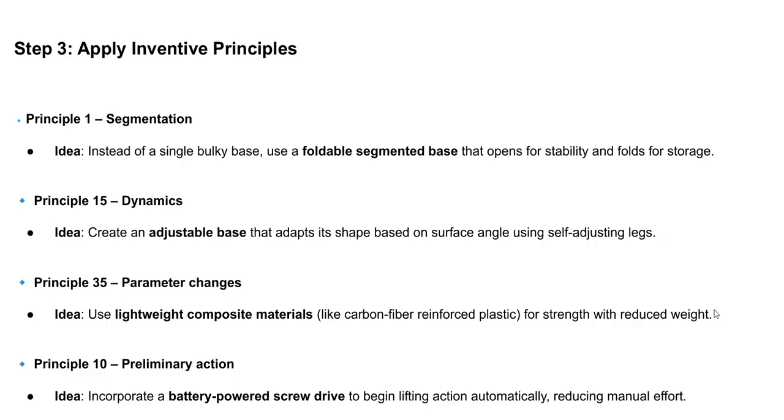Step number 3 is to apply the inventive principles. First principle, segmentation: instead of a single bulky base, use a foldable segmented base that opens for stability and folds for storage. Principle number 15 is dynamics: create an adjustable base that adapts its shape based on surface angle using safe angle adjusting legs.